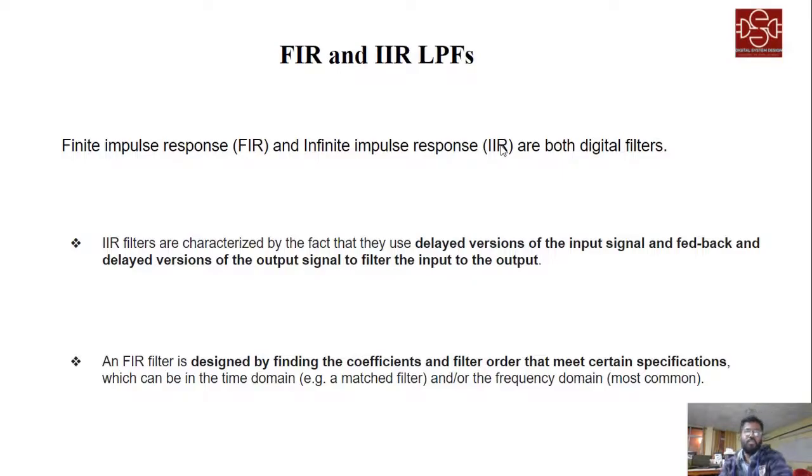Now moving on to the FIR and IIR low pass filters. From the name we can see that FIR is the finite impulse response and IIR is the infinite impulse response. Both are digital filters. The IIR filters are characterized by the fact that they use delayed versions of the input signal and feedback of delayed versions of the output signal to filter the input to the output.